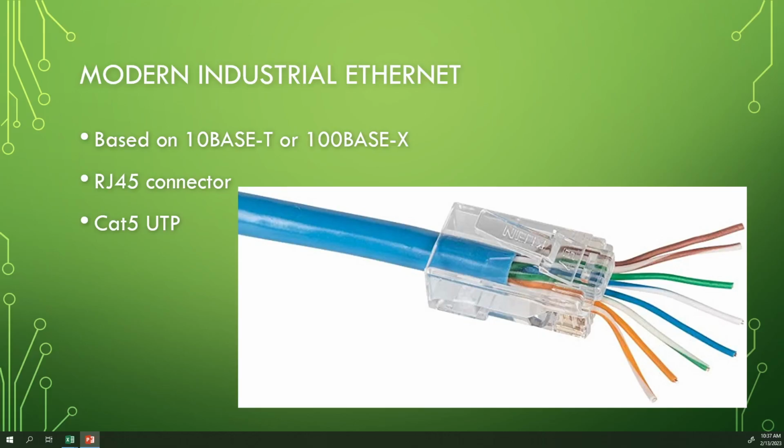And this says, despite its inherent resistance to electromagnetically induced interference, unshielded twisted pair is not really suited for industrial applications. Right? Hence that green wire that I was showing you guys before this recording, or how it has that extra shielding on the outside. So the case here actually has metal on it, so it can be shielded into the switch or whatever, and then that connects to the outside of that coating. One of these days, I'll probably cut one of those cables in half so you can actually see that right into it. But we'll come back to that one.